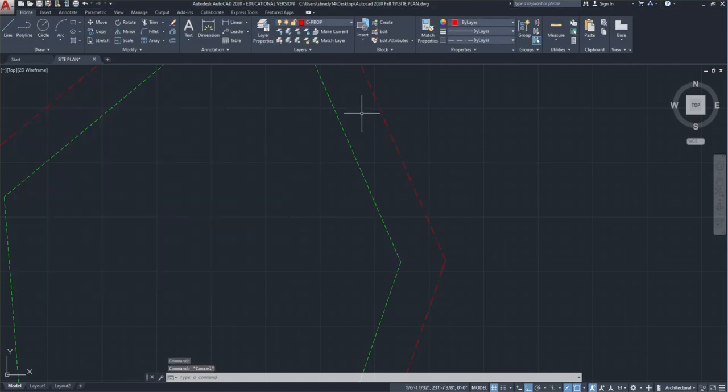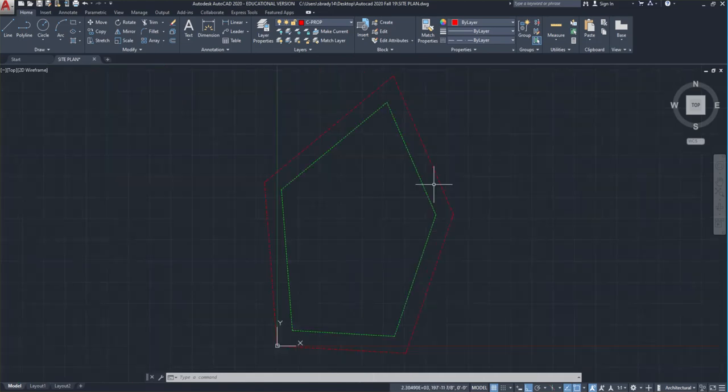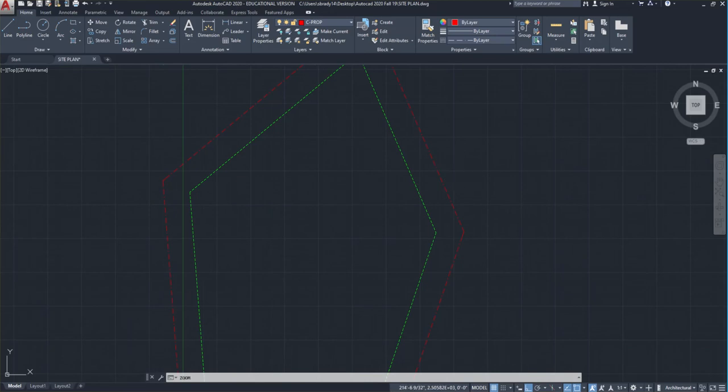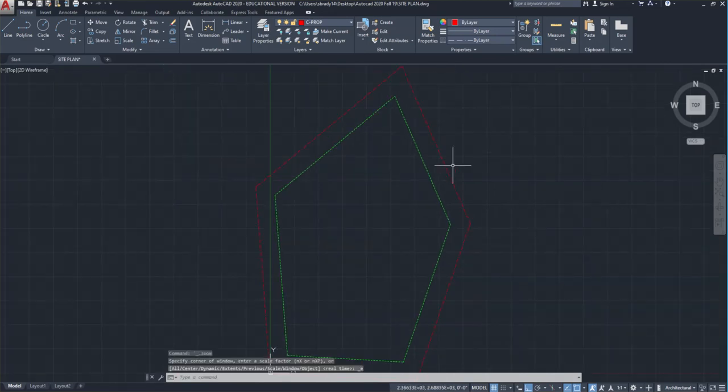I say all these things very easily, like, oh, remember these 800 settings in AutoCAD, right? And I only remember them because I've been doing this for such a long time. So I'll continue to remind you about these things as we continue drafting and learning different things in this course. But there are a lot of settings. You open a drawing, you create your layers, you draw your layers, you're in decimal units, but you have to set your units to surveyor units for that to function. You create your drawing, you have to scale it, then you have to change your units to architectural, and then you have to print it, which means changing a setting of LT scale. There's a lot of things to remember in this one little site plan.